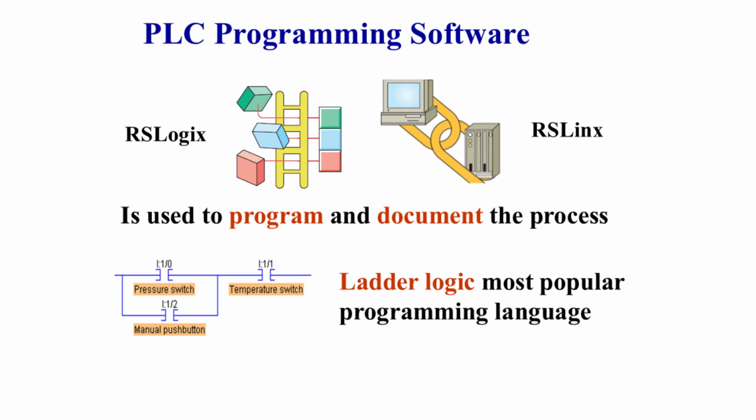The most popular programming language is ladder logic, shown here at the bottom of the slide. Ladder logic resembles electrical relay diagrams, making it easy for technicians and engineers with electrical backgrounds to learn quickly. Together, this software allows us to both program the PLC and visualize how the system is functioning, which is critical for both operation and troubleshooting.